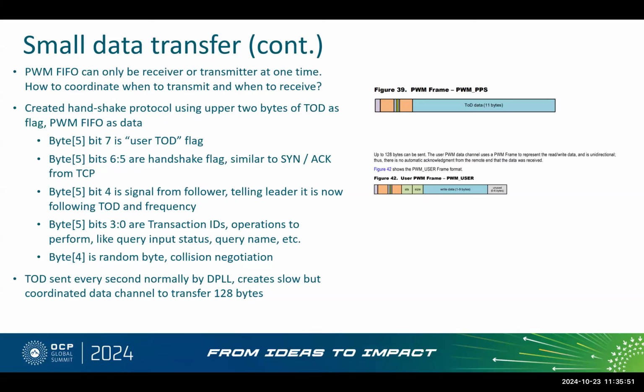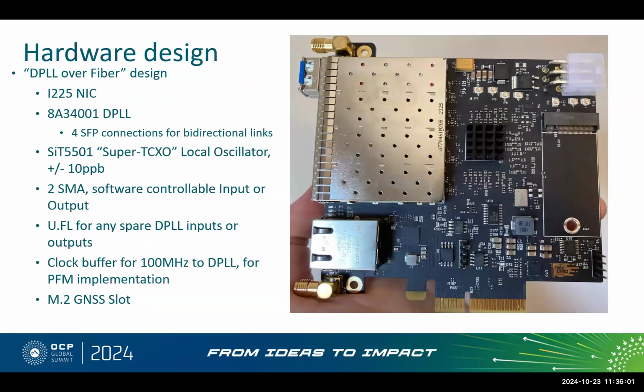So you're using the DPLL outputs basically as the clock signal being transferred directly to the SFP. The SFPs alone are fairly straightforward. They pretty much just take a differential LVDS input and convert it to optical, and give you LVDS output. That worked once I played with the termination scheme well enough. It pretty much worked straight out of the gate: a fast enough frequency from the DPLL as a differential output goes through the SFP clean. So the optical part is pretty straightforward.